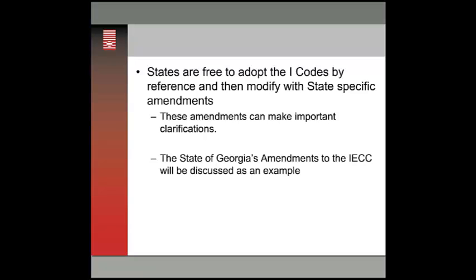Typically what we see happen, like the state of Illinois adopted the 2012, but they tweaked some of the numbers. They didn't go with the 3 air changes at 50 because it was their first foray into code enforcement with the tightness levels. They changed it to 5 ACH50, and a lot of states are doing that.